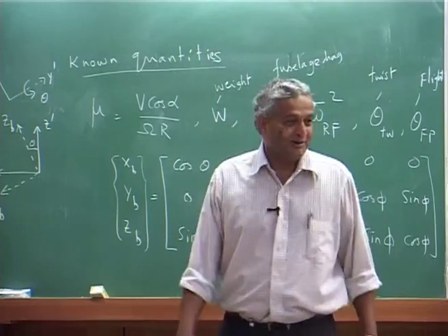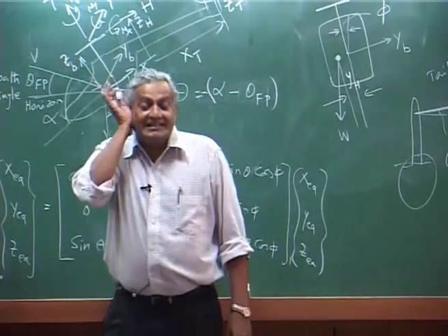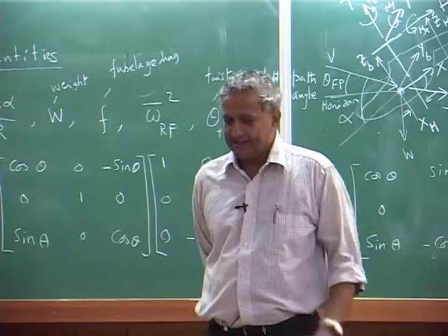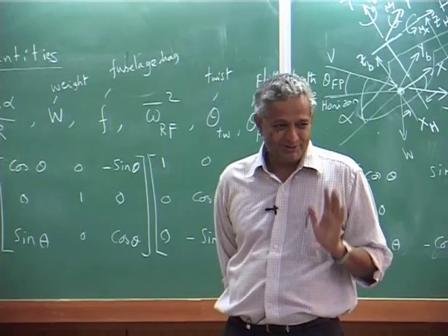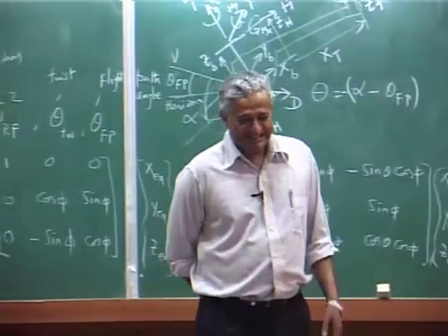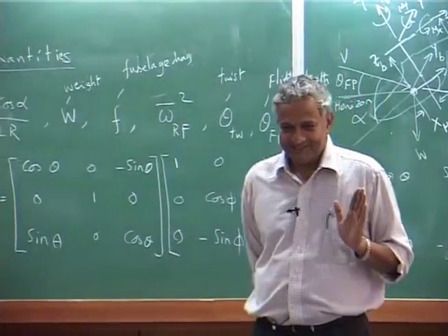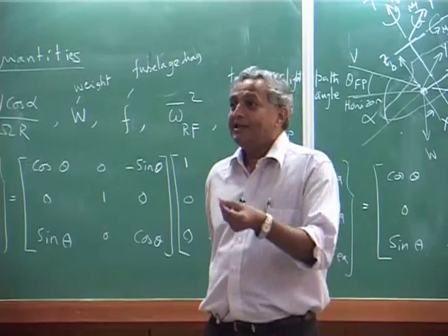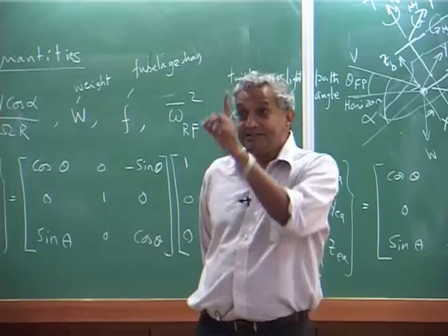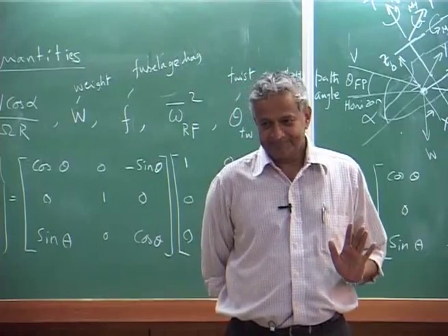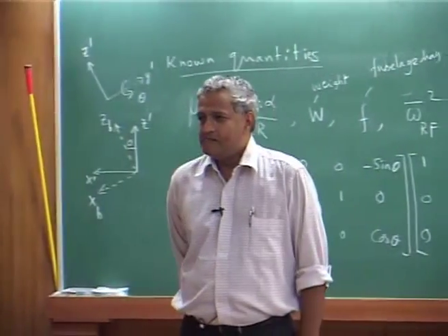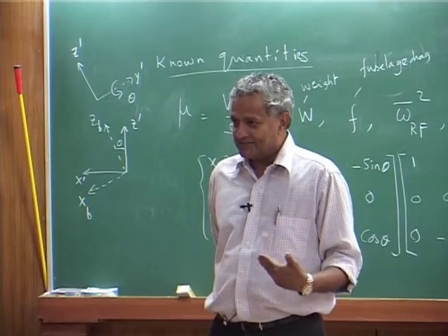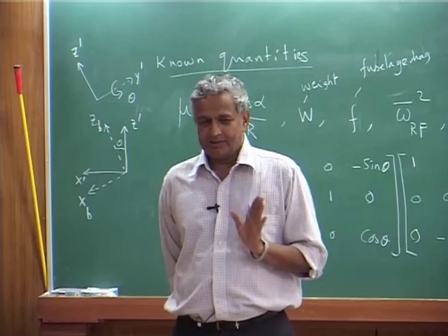Why? A component of the tail rotor thrust you can use in supporting the weight, that is all. But usually cant is not done arbitrarily, not everybody gives the cant. The advantage is that I can use a component of the tail rotor force in the vertical direction. Is there a limit for changing the cant? No, you can't change it, it is fixed in the design configuration, but not all helicopters have it.